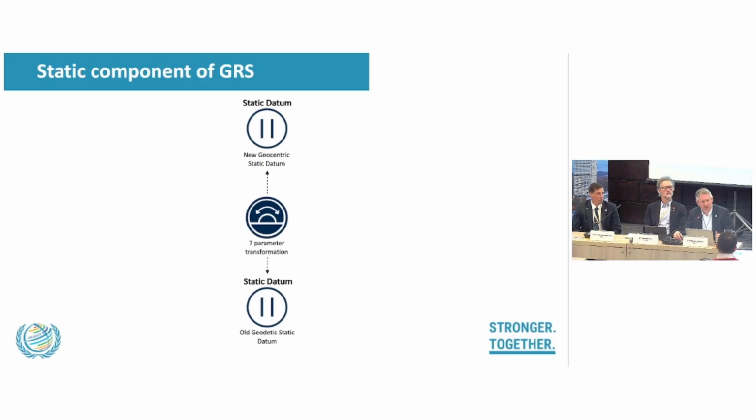Okay, thanks for explaining. This is a great example of where the country, in this case the Netherlands, has done the technical work to allow the user to be abstracted from the complexities of the geodesy. They've done all the technical steps and put the standards in place to allow them to take real-time data and then transition back to an old datum.